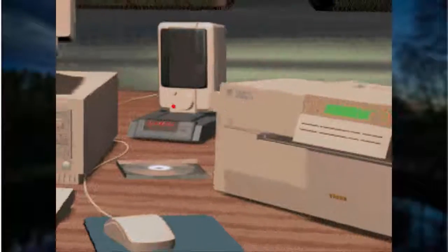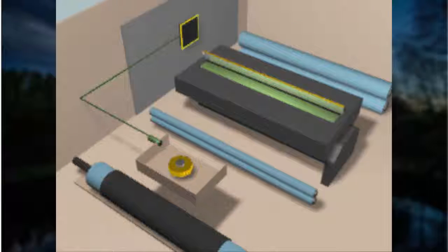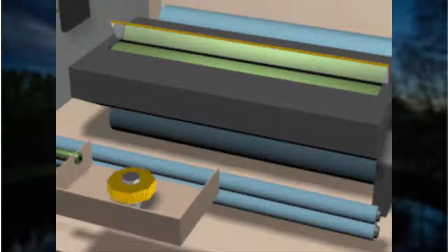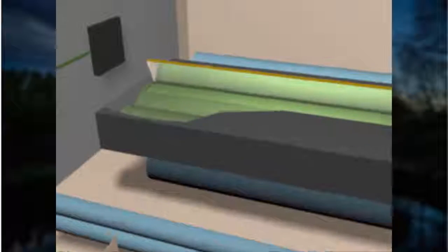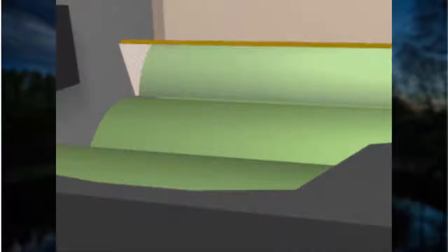Software in the computer tells your printer what text or images to print and where to put them on the page. Inside the printer, a special processor powers on a tiny but precise laser light. A spinning mirror sprays the laser beam in a thin line across the print cylinder or drum. This drum is charged with static electricity and is also covered with a light-sensitive material.